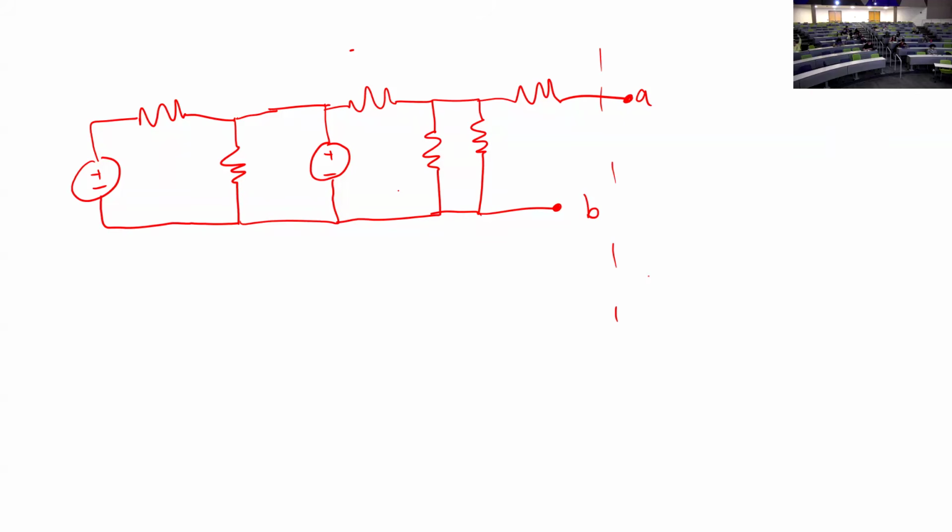If it's not asking you explicitly and telling you where to do it, you can choose to do that. For instance, in this circuit, I could draw, say, call this A tilde and call this B tilde, and make this problem easier for myself and solve for the Thevenin equivalent of this, or the Norton equivalent of that. And then I plug this into where my A tilde and B tilde are, and then I solve it again in whichever order I want. It's just taking anything and making it simpler.